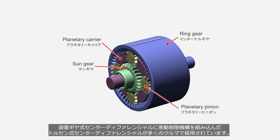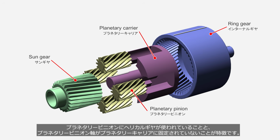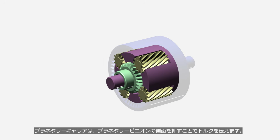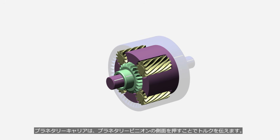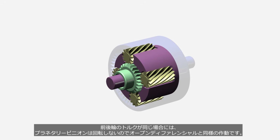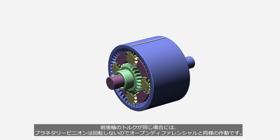Many vehicles use a torsen-type center differential that integrates a limited slip mechanism into this planetary gear center differential. Its key features are the use of helical gears for the planetary pinions, and the fact that the planetary pinion shafts are not fixed to the planetary carrier. The planetary carrier transmits torque by applying force to the sides of the planetary pinions. When the front and rear wheel torques are equal, the planetary pinions do not rotate, so the differential operates in the same way as an open differential.